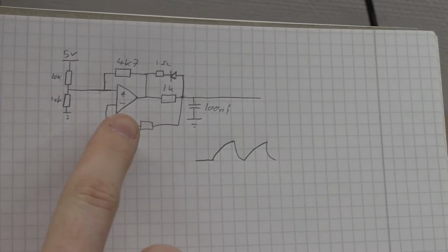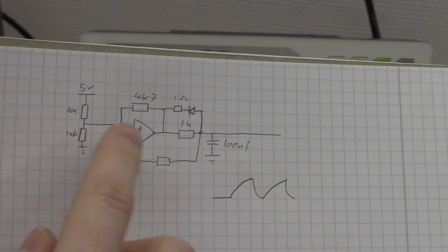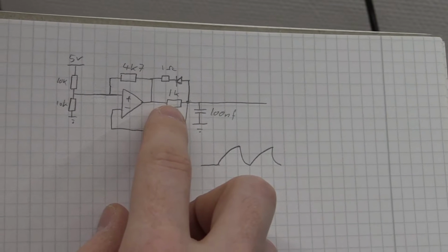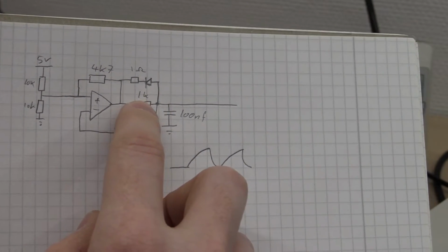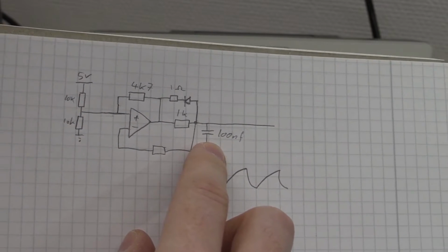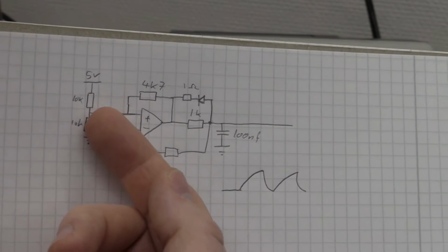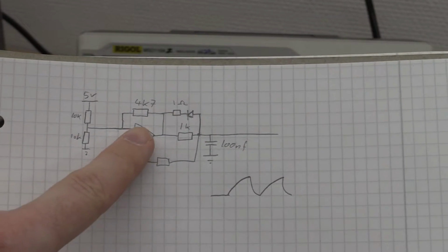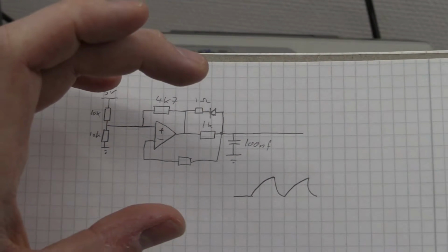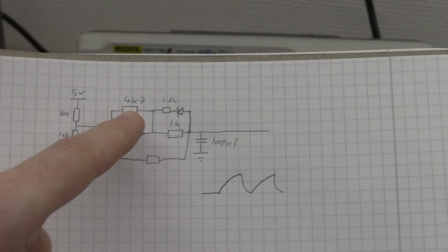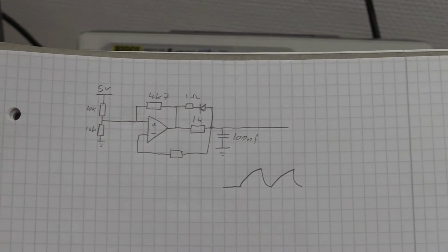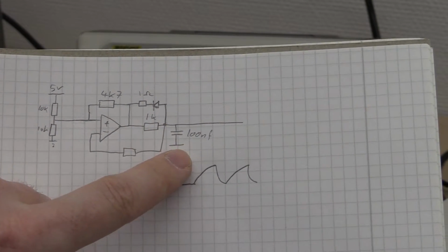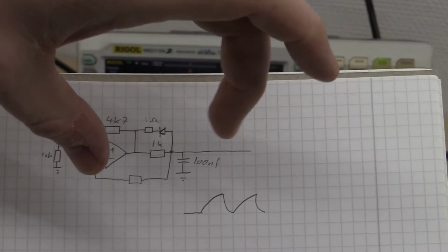And the frequency, you can calculate it if you want. I didn't really bother, I just tried something, but it's the RC time constant of this resistor and this capacitor over the voltage range that you set with the division ratio here. If you increase this resistor, you will squish the peaks together, making a faster wave also. If you change either the resistor or the capacitor, you will have the same amplitude but only change the frequency.